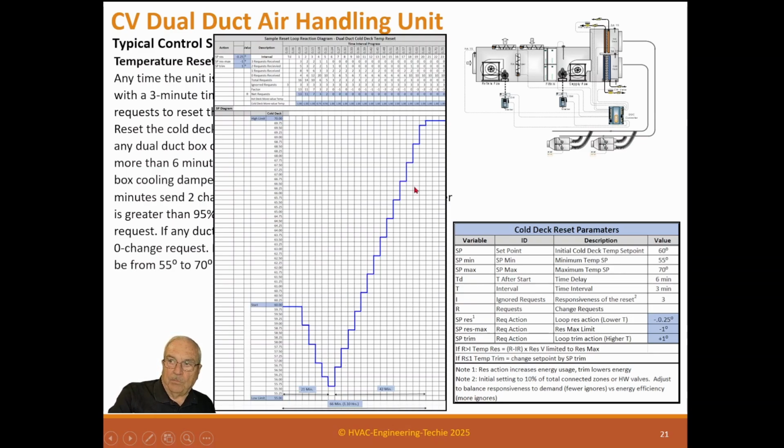Now, it will never operate like this, but what I'm doing is trying to tell what is the maximum time limits to get from here to here. And you see this was only 21 minutes, and my parameters try to do this within a half hour. What I'm trying to say is you don't want the customer to say, wow, it takes a long time to change the temperature, nor do you want it too quickly because it'll overshoot and it will use more energy.